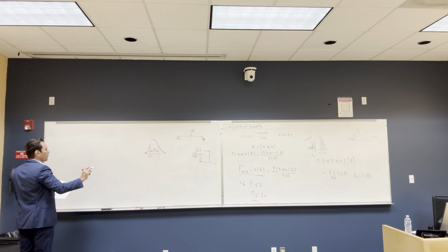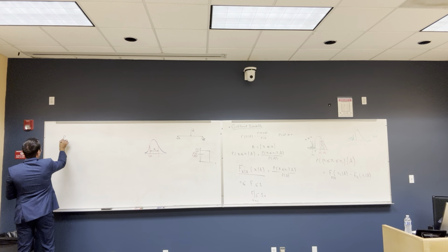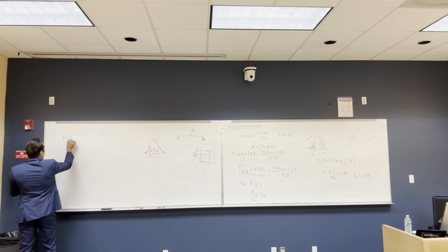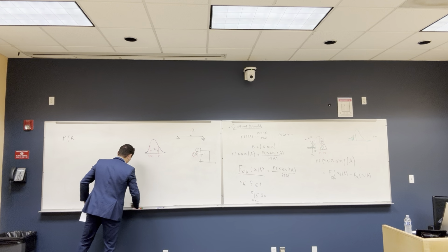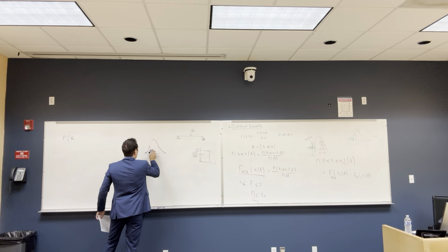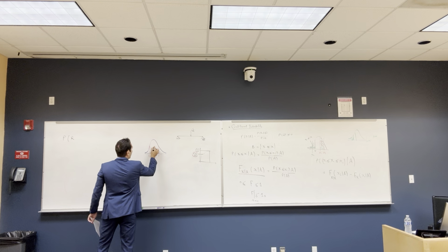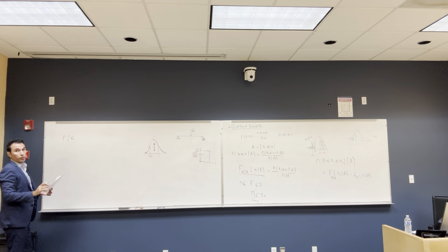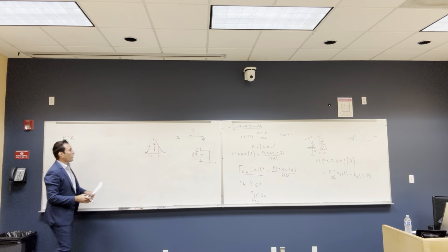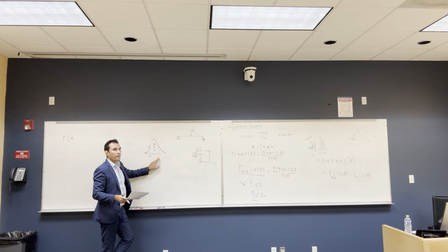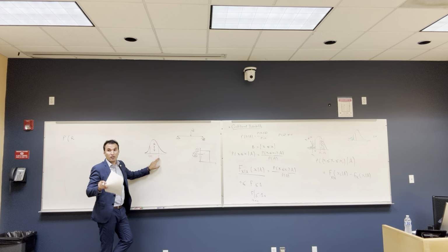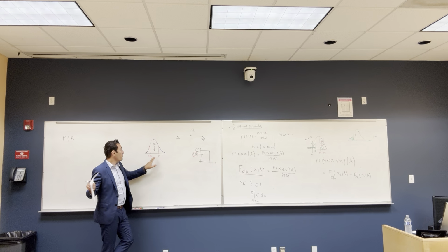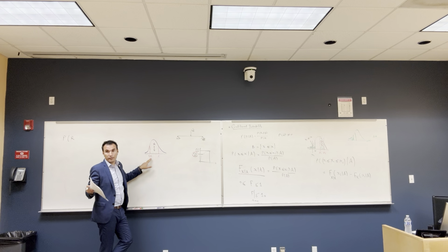Let's write this in terms of a probability. I'm looking for the probability of R. R is my random variable. What's small r and big R? Small r is the assigned value of the capacity of the beam. Capacity is the rupture load. And the beam is not ruptured. The beam shows signs of deterioration, so it's uncertain. But this is the proof load, or we call it the yield load of the beam.